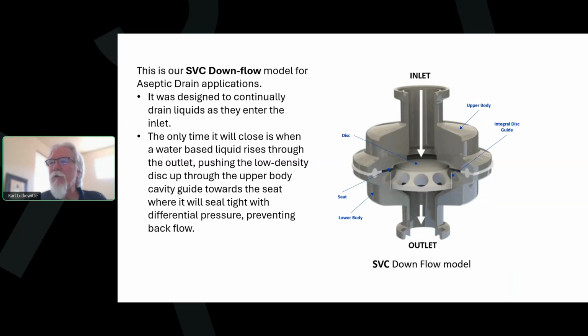They could not use a spring check in the drain lines under the sinks, of course, because with a spring check valve, I'm always going to have a dead leg of fluid sitting in that drain above the poppet, because even with a low half PSI cracking pressure, for example, which I think is one of the lowest that you can get on spring check valves. That means I'm going to build up at least 8 inches of water column in that drain that will never drain because it's not enough weight to open the poppet on the spring check valve. So he couldn't do that.